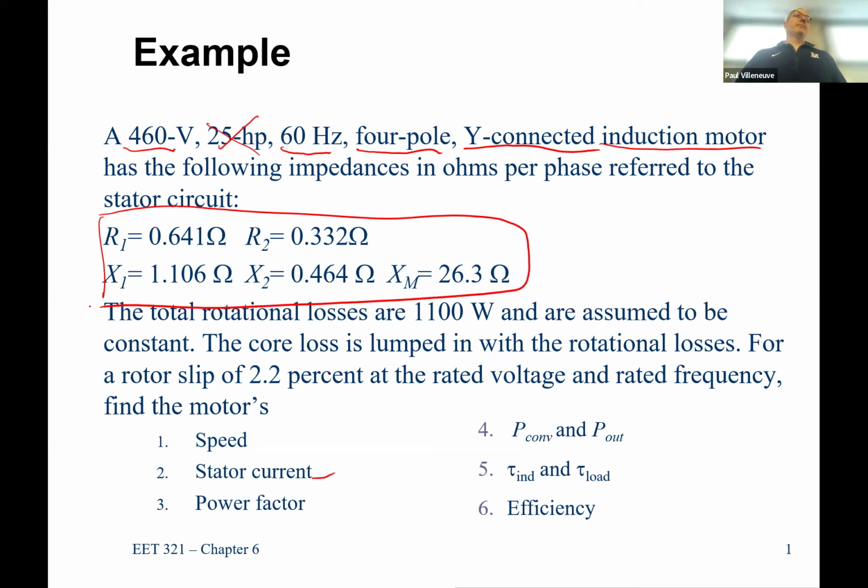How do you define the torque? That's true, but our mechanical engineering friends would tell us that there's a speed versus torque characteristic, and depending on what speed you're operating at, the torque changes. If you think about a pump, as you increase the speed, you need more torque because you're pumping more water, until you get to right about here. And then when you're pumping a lot of liquid, you get cavitation.